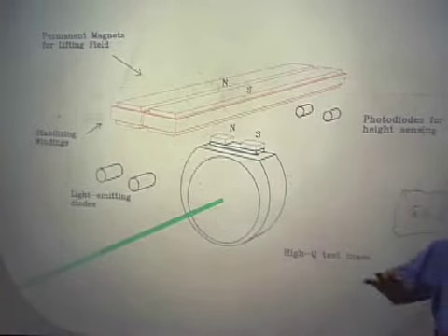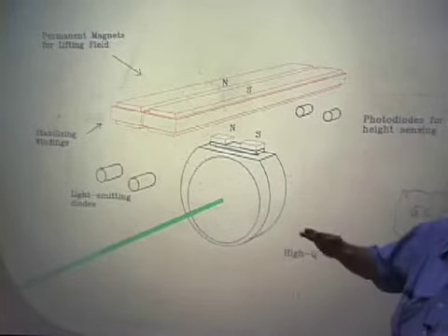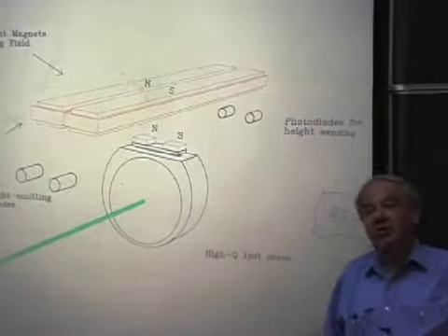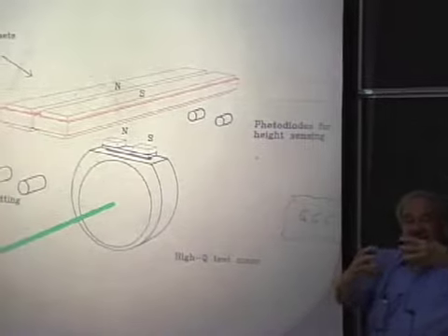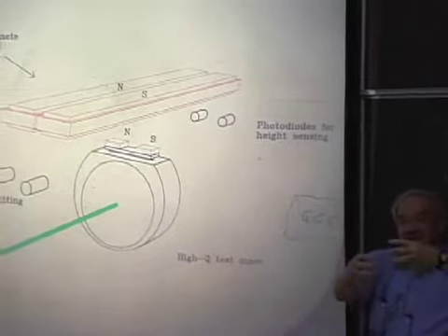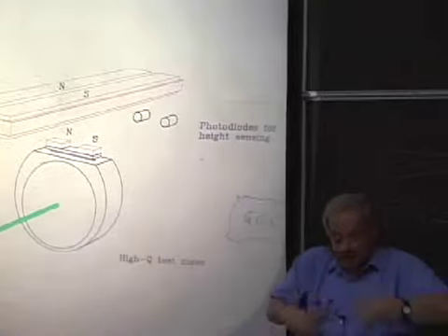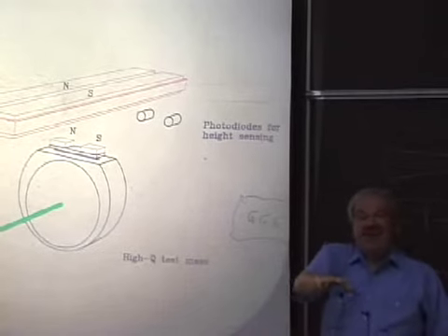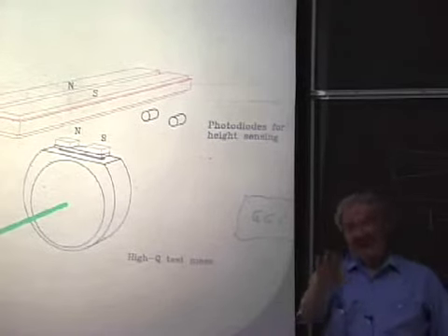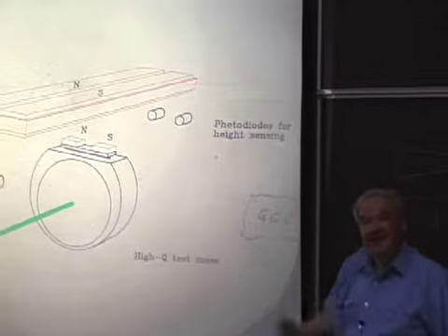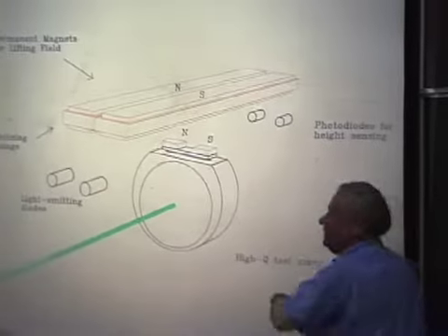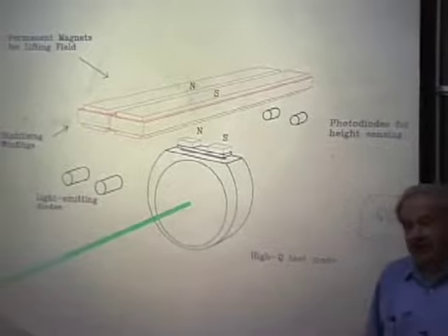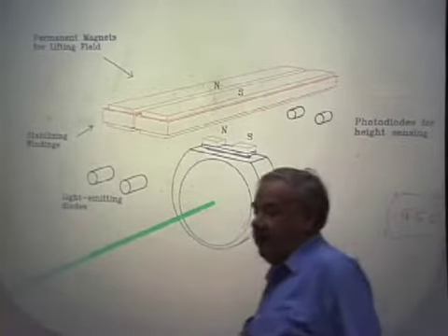As soon as you get that working, what you find is, of course, with this long period, it's very sensitive to tilt. If you walk into the room and this thing is there, the thing has to come towards you. But it's not because your weight's attracting it. No, it's because you're depressing the floor, even though it's a basement, solid floor. It's tilting the whole thing, and the thing is running downhill towards you, and that's why it comes towards you. So such a thing with a long period is very sensitive to tilt to the ground. So the next step is to control that, and that's what we did.